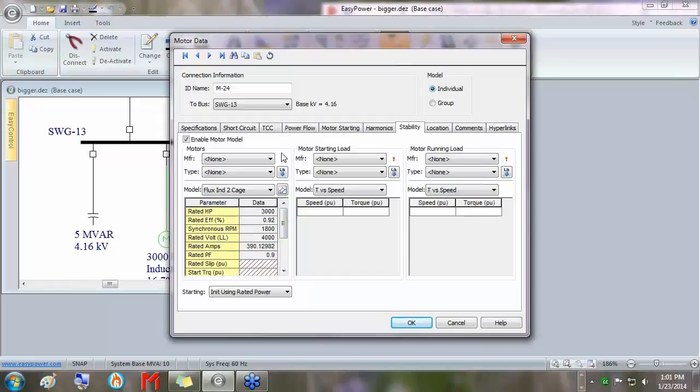Well, given we don't know how to fill in this information necessarily, do you know what the armature resistance, armature inductance, L, X, X prime, X double prime, T prime 0 are? Those are parameters that we hear about when we talk about synchronous generators and getting generator data sheets. So it's kind of odd that these are what we need. But again, we're putting together a fully detailed flux model.